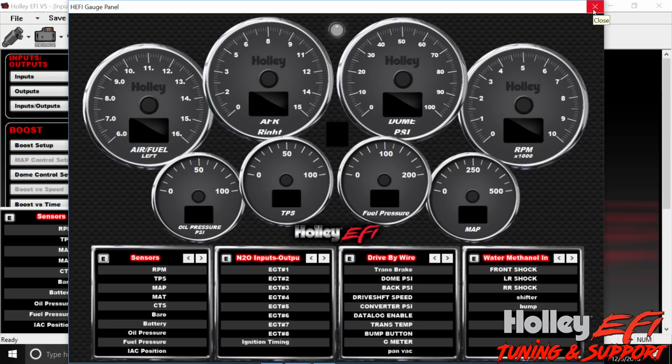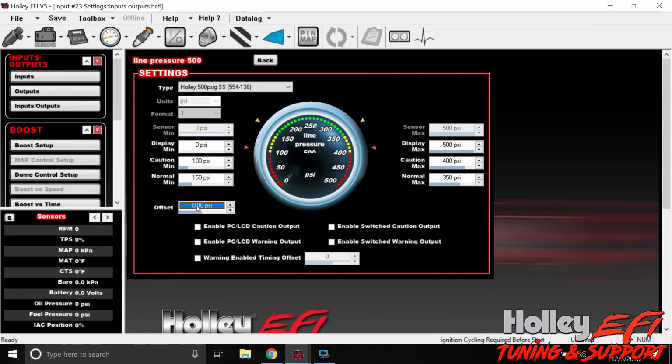But when you go in here and there's 0 pressure on the transducer, if it reads say +2 psi, you can offset this with -2. So it'll read 0 when there's no pressure on it. So this is just a quick way to offset the transducer.